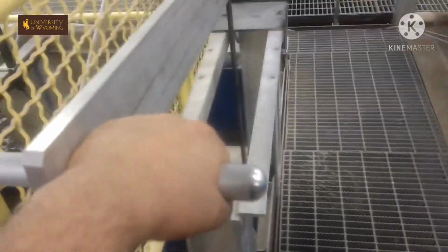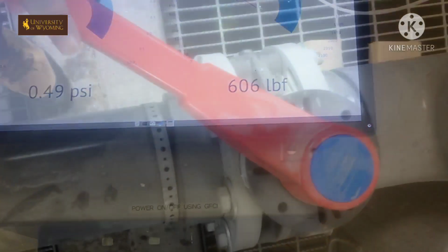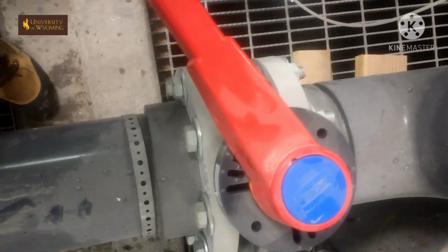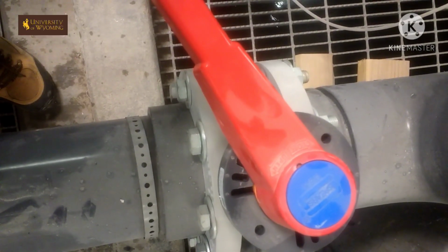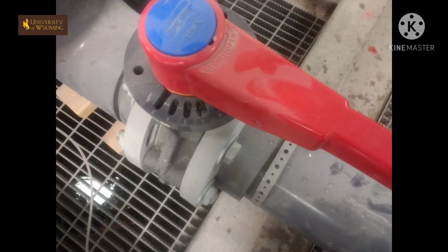The control of flow to the bucket is done by the gate, and we also need to close the exit valve of the bucket to calculate the discharge rate. The weight of the bucket is noted from the display monitor. The control valve controls the discharge, and this control valve has 7 control points starting from 0 to 6. We have started our experiment from the position of maximum discharge.